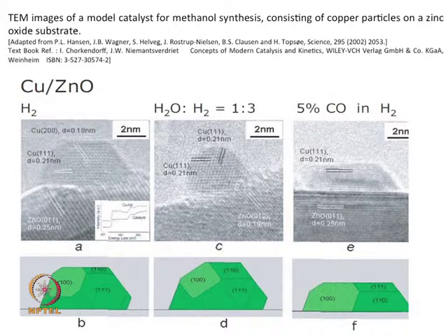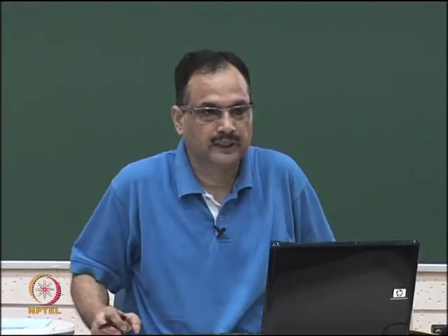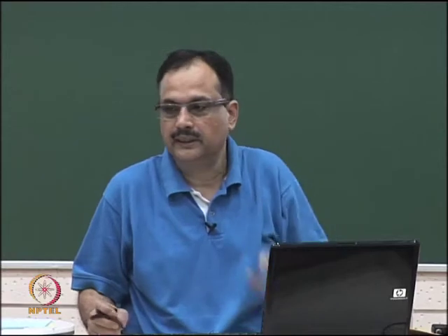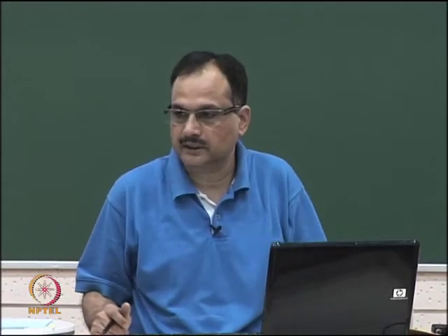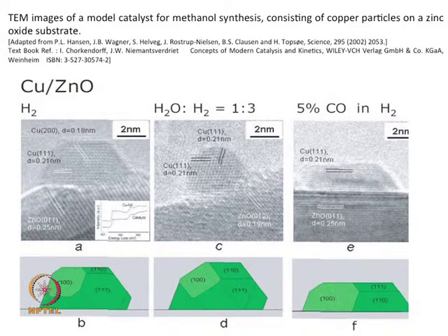Body. So, when you see different orientations of a lattice, the x, y, z planes, and how an atom has been arranged in a plane, that structure can be identified. So, when you have a time plane, you can see here that this is one kind of zinc oxide, you can see a boundary here. So, you can measure the crystal size of zinc oxide also, by just looking at this distance, because this distance is 2 nanometer.